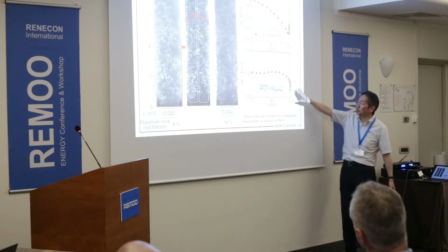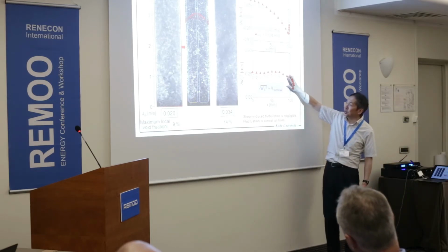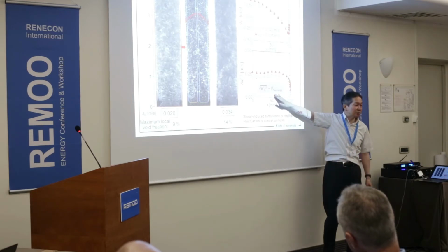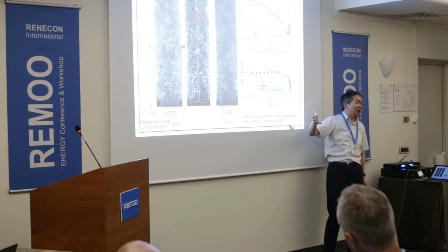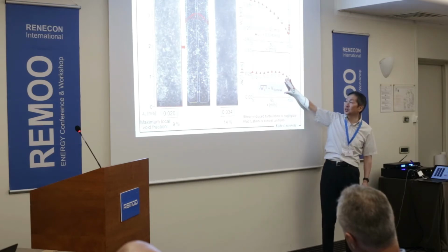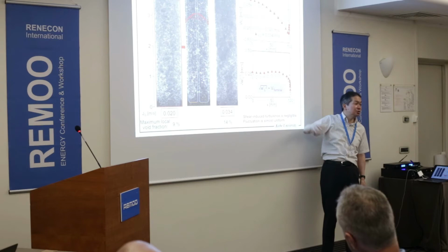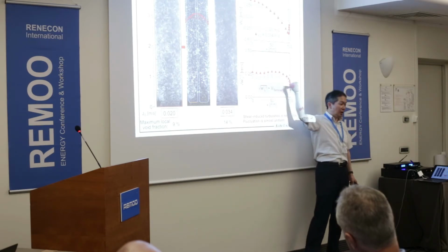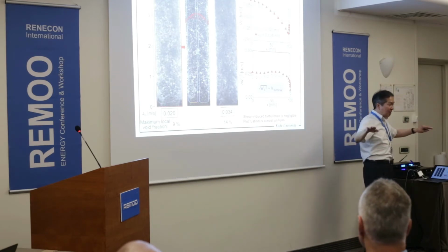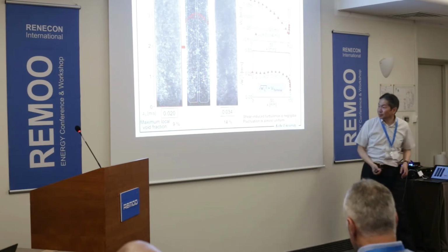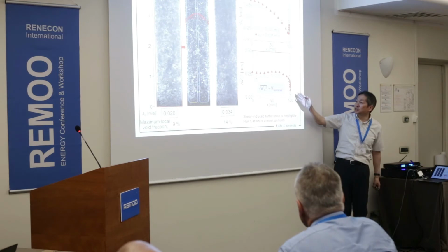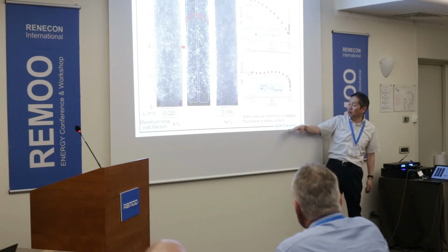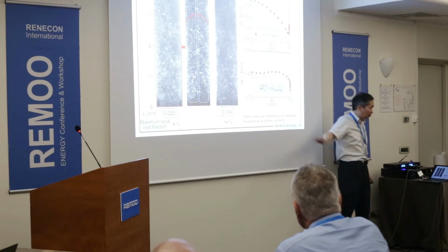And this is the turbulent intensity. It's more or less close to the bubble terminal rising velocity. 0.23 is a mean value of the terminal rising velocity, so the main fluctuation is due to the velocity sweep, in this case, across the cross section. So from this, we can see that shear-induced turbulence is very negligible, and the fluctuation is almost uniform.